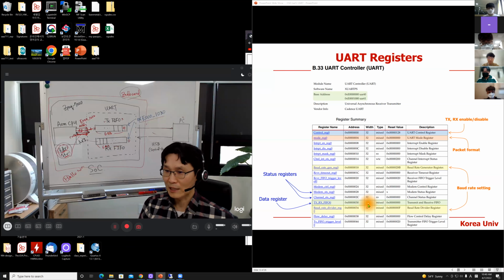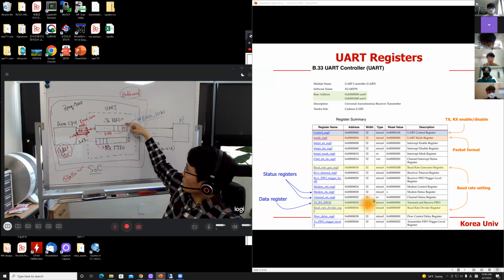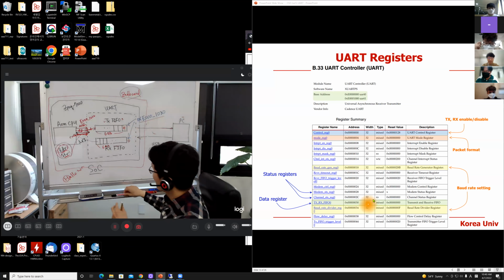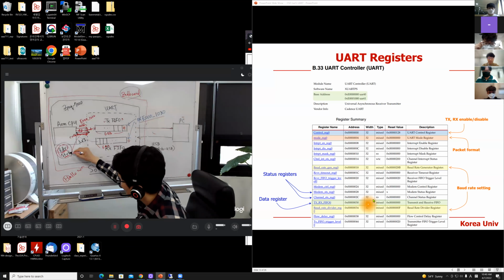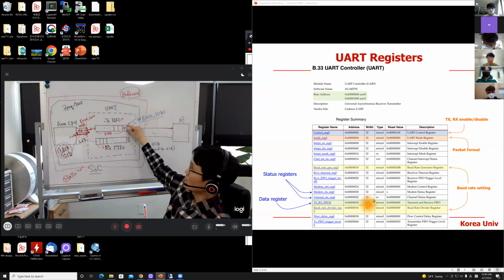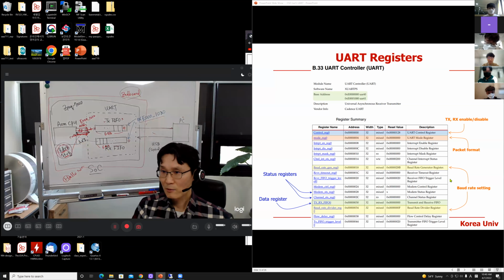It's supposed to be 8-bit because each one is a byte. So it is talking about individual bytes. You are programming an individual byte with STRB or LDRB. You are supposed to use a byte access instruction because you are programming this specific byte.